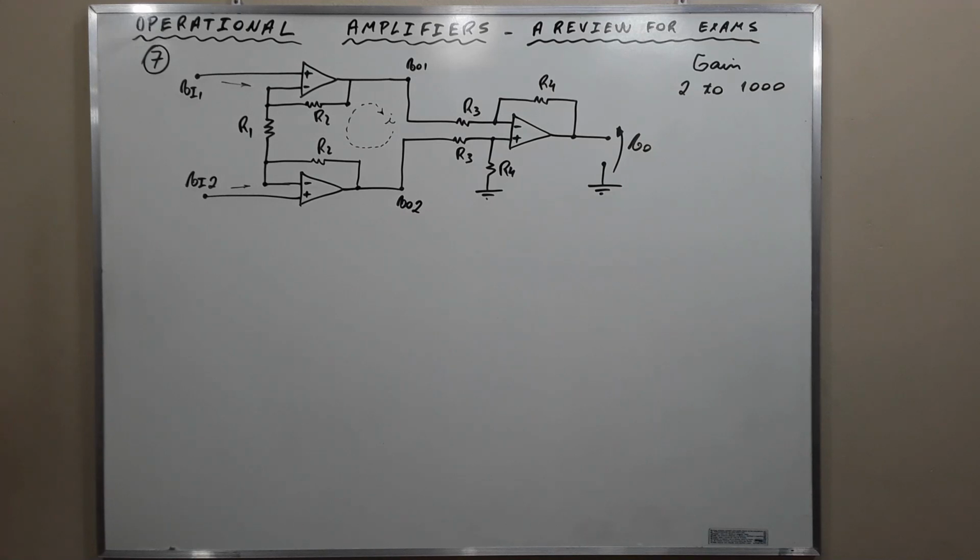We are going to assume the strategy of designing the instrumentation amplifier in a way where all the required gain is obtained in the first stage, leaving for the second stage the task of letting pass the difference between the outputs of the first stage and rejecting the common mode signal.